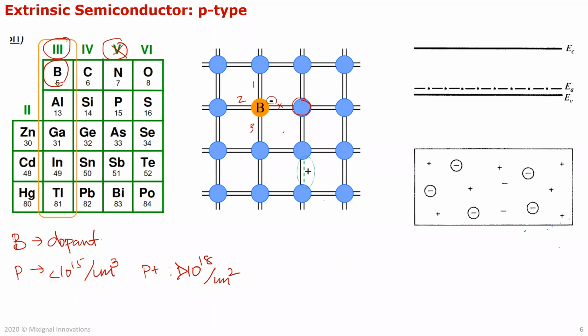So which means that it creates a hole, because now some other electron can come in and fill in here, or for example, fill in here. So that looks like as if a positive charge is moving in. And if you look at the band diagram, because it is positive, the energy moves in the opposite direction. So if you have a lot of positive charges, then the Fermi level will actually move in this direction, because if you have positive charges here, then you can conduct here.